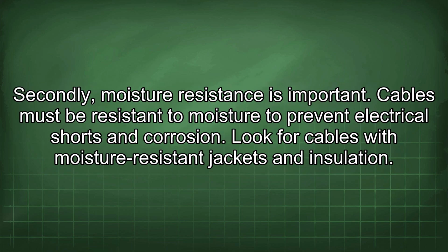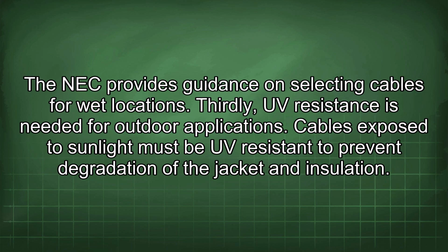Secondly, moisture resistance is important. Cables must be resistant to moisture to prevent electrical shorts and corrosion. Look for cables with moisture-resistant jackets and insulation. The NEC provides guidance on selecting cables for wet locations.